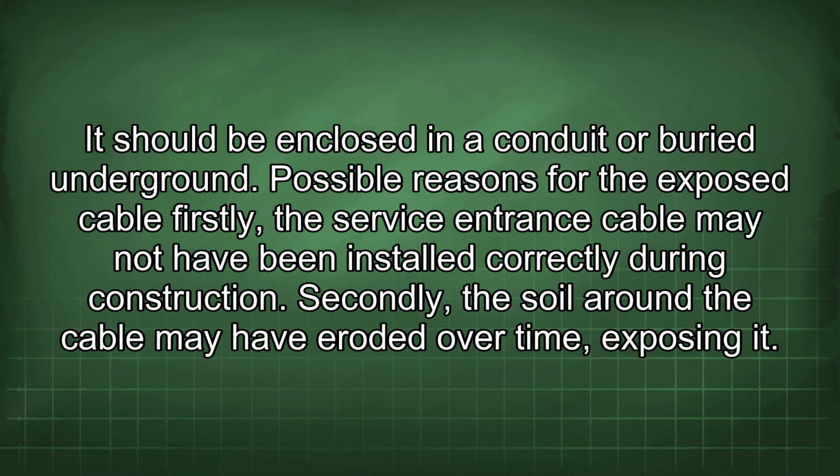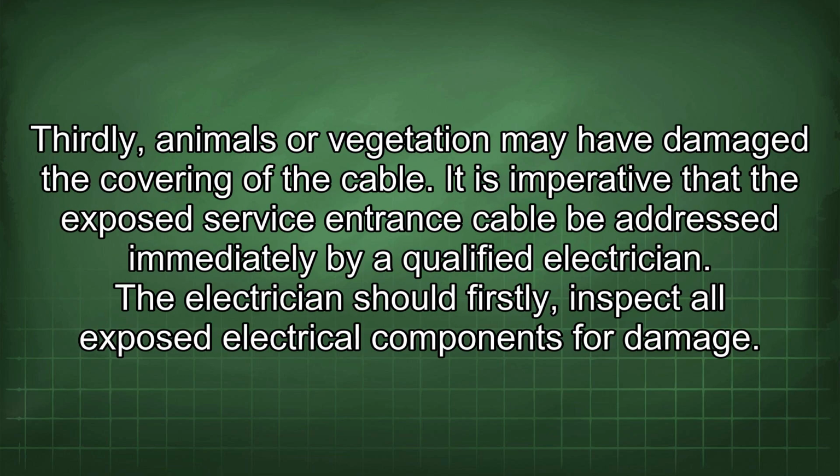Possible reasons for the exposed cable: firstly, the service entrance cable may not have been installed correctly during construction. Secondly, the soil around the cable may have eroded over time, exposing it. Thirdly, animals or vegetation may have damaged the covering of the cable. It is imperative that the exposed service entrance cable be addressed immediately by a qualified electrician.